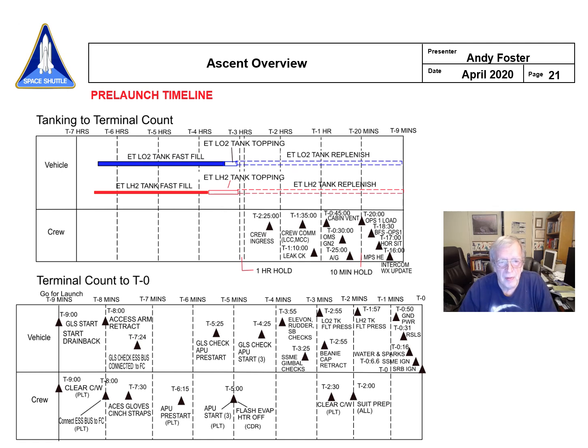So we would start off the tanking up here at T-minus 6 hours, about 6:30, with what we call the fast fill. We're putting the propellants in at a high rate, filling those big tanks up. And as we get them toward the top, then we slow down the rate, and then we top them off. You can see that right here. And then there's a 1 hour hold in here. Not much going on in there, but essentially what you see here is replenish. These are cryogenic propellants, so they're boiling off, and so we're just keeping a fluid flow in there to keep the tanks topped off while we count on down.